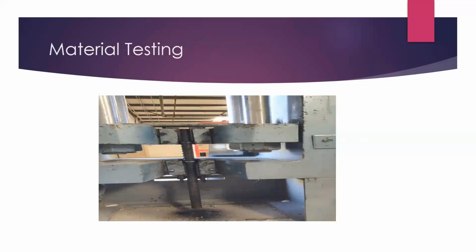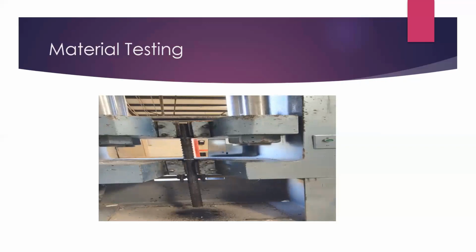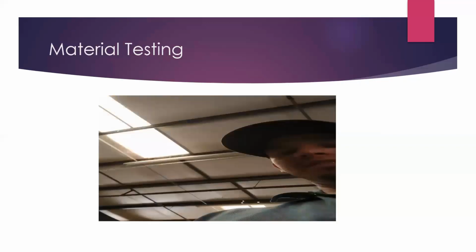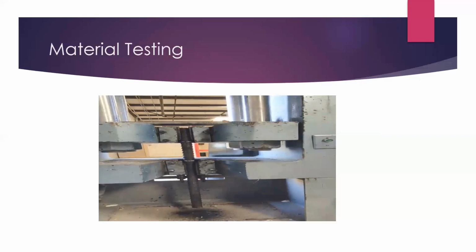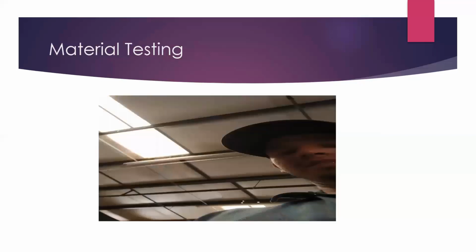So also note that there are two white lines drawn on it that are moving. There we go. They're moving away from each other. You want to watch it one more time? One more time. Okay, so in the beginning, it doesn't look like it's moving much at all, but then you start, and so that would be like our elastic region where we're applying more load, but it doesn't have a lot of displacement, and then it starts to have a lot of displacement. So you can see there a lot of elongation, and eventually it ruptures.